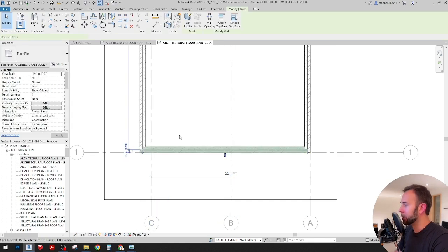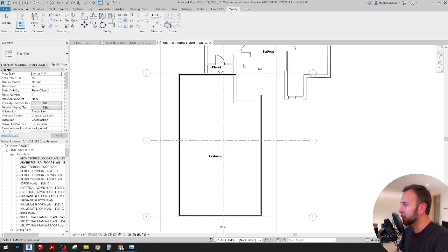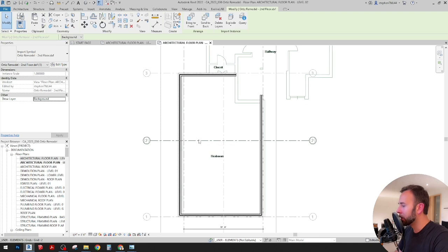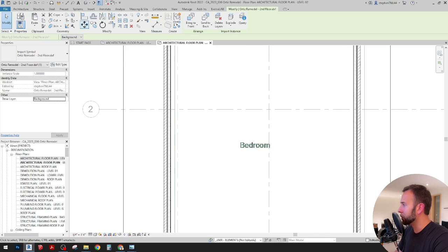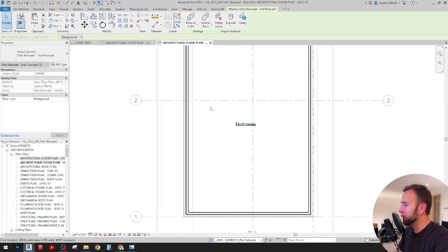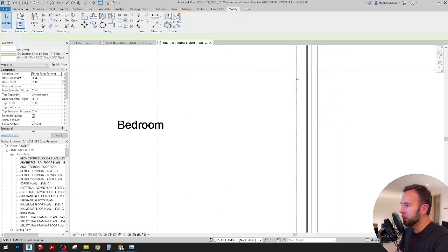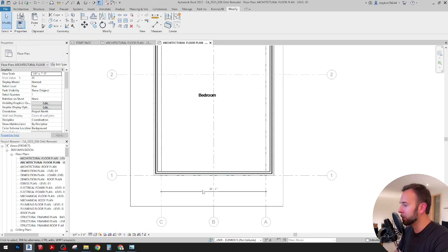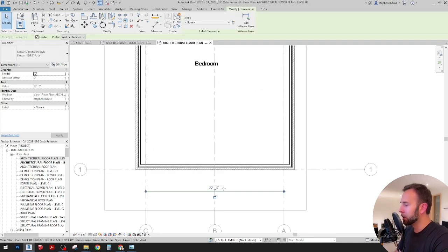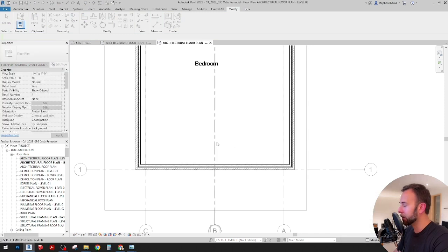And after I do that, I can just make adjustments, basically shift this to align with that new stud wall. So again, I'm going to take the actual drawing and move it over that's underneath. And I can see if, yes, my drawing underneath is in fact lined up with the 22. We'll remember to just recenter this by editing the witness line, grabbing that. Okay, so it's already locked in there. It's constrained, so that's good.